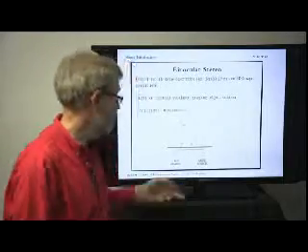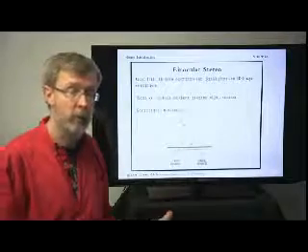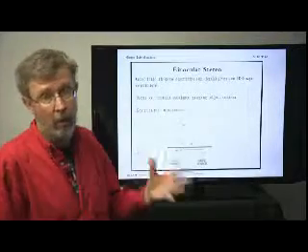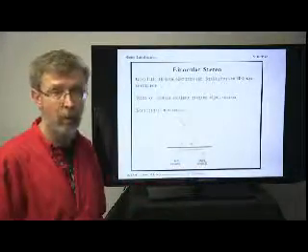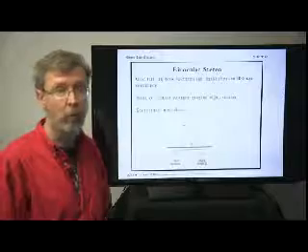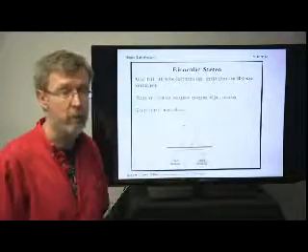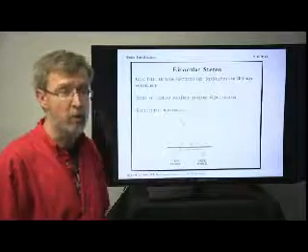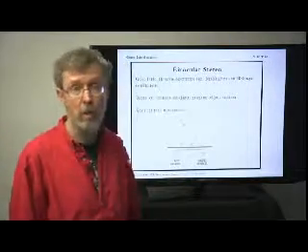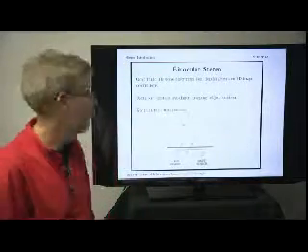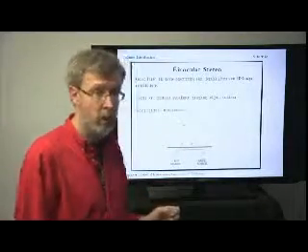Now, why are we interested in this sort of three-dimensional calculation? Well, here we're going to be interested in object recognition and location. And once you have that location, you can get a robot to go in and grasp it if you're doing some kind of machine assembly type work, or spray painting or inserting glue or components or something like that. A robot could also use this for obstacle avoidance, because you can tell where the obstacles are in the scene, and therefore navigate around them. So those are some of the kinds of applications that you can do with this sort of stereo system.